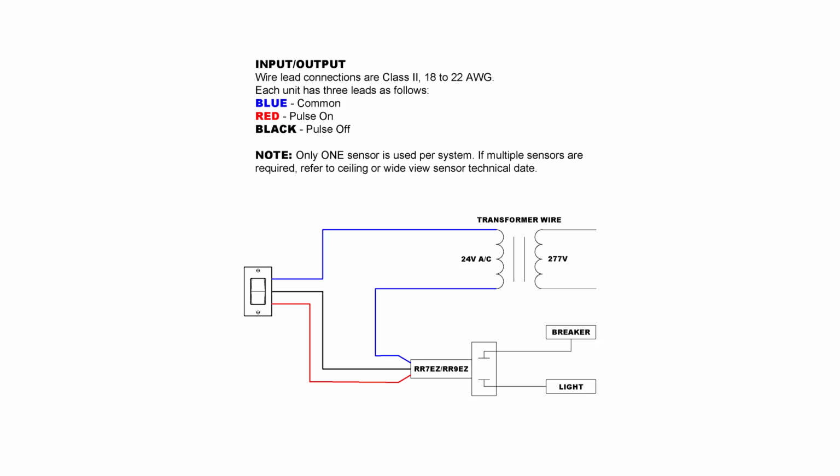It will say that RR9 has 2 extra yellow wires, which will connect to the low voltage controller. Now we use the low voltage controller to turn the relay on or off, and we also use a light switch. You may have a light switch in the hallway and in the tenant suite. Okay, so that's the connection between the relay on the low voltage side.